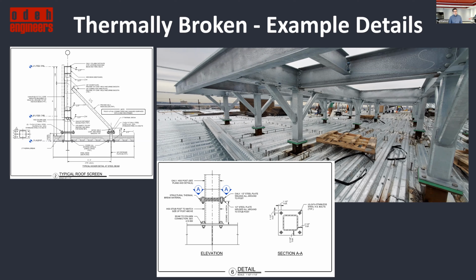But again, this is a thermal break pad sandwiched between cap and base plate, the height of which is coordinated with the architect in terms of the location of the roofing membrane and the insulation layer. But you can see that as long as you can minimize or design the connection to minimize the compressive stress on the pad, these details are not that difficult to come up with.